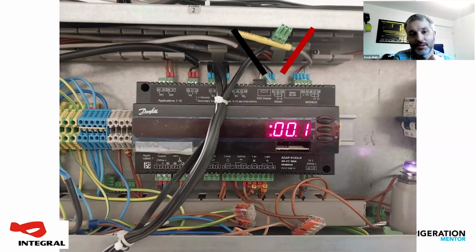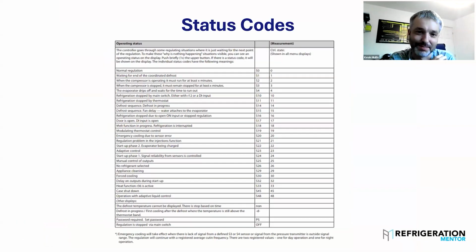It's worth having a look, see if you've got a voltage difference there as a little indicator. But network fault finding, and I've done a lot of network fault finding over the years, is very much an exercise in organization and logic. Look where you've got things that are talking, look where you haven't got things that are talking, and then upset the store manager by telling them you need to get in the ceiling in between them, usually. Yeah. But it is worth checking.